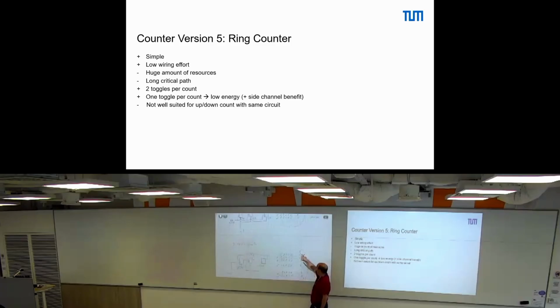Now if we look into this regarding frequency, it's roughly the same. Here we only have an inverter in addition. That's the only logic we have on top. Roughly it's the same frequency we can count. What about power? It's even lower power because at a time we only toggle 1 bit. So it's effectively a better choice than this one-hot counting.